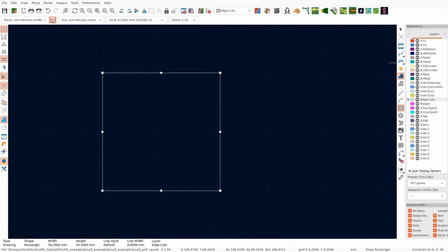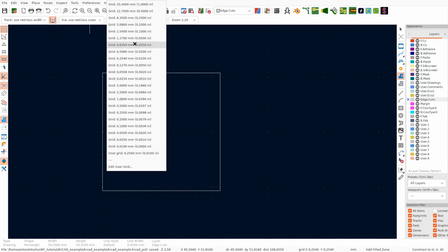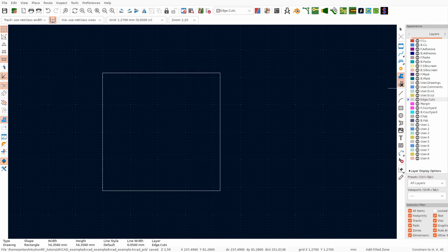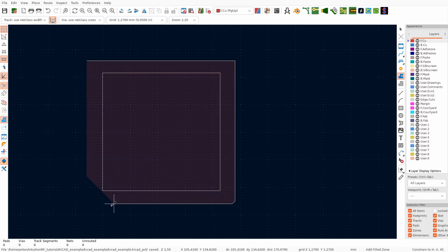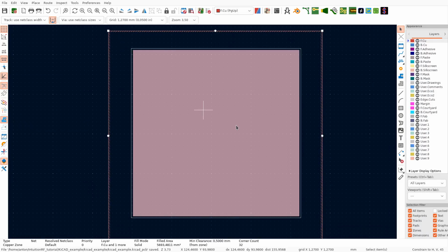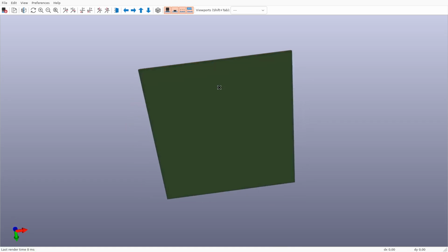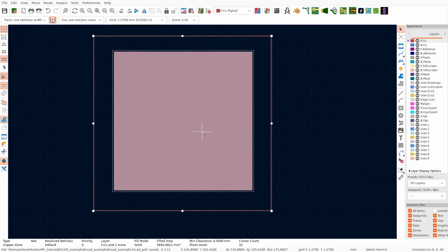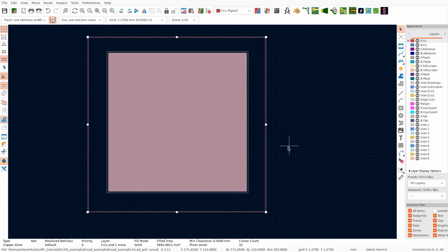Let's add a copper pour on the, sorry, like this. Okay, on both sides, like this. Oops. Okay, so that's our copper. We should see it on both sides. This is correct. It's a 2-layer PCB, but we could do the same with 4 layers. And now let's add some traces. I'm going to make them quite large so we can easily see what's going on.